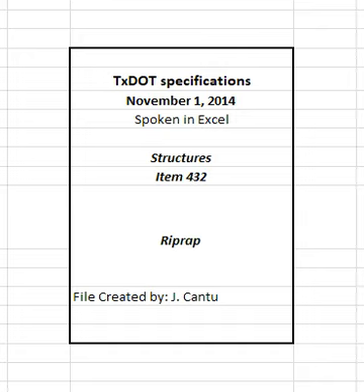2.3.4 Protection. Use boulders or quarried rock that meets the gradation requirements of Table 1. Both the width and the thickness of each piece of riprap must be at least 1/3 of the length. When shown on the plans or as approved, material may consist of broken concrete removed under the contract or from other approved sources. Cut exposed reinforcement flush with all surfaces before placement of each piece of broken concrete.